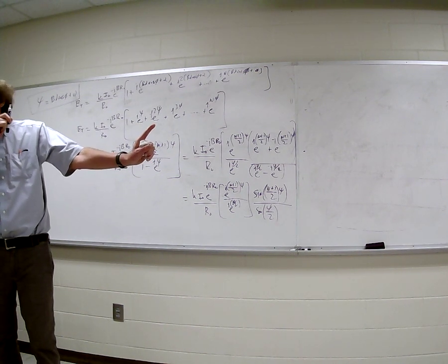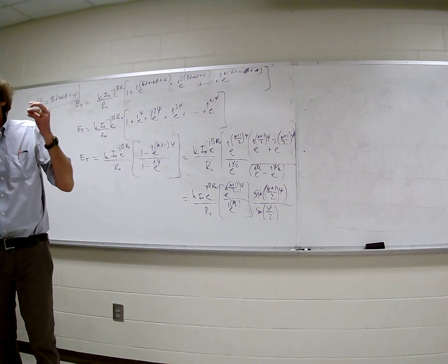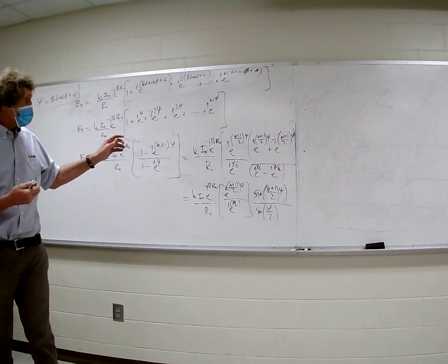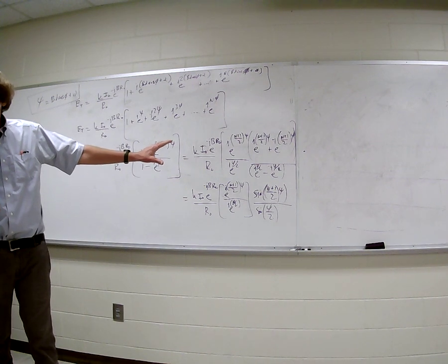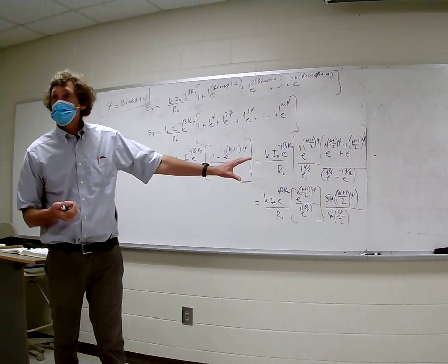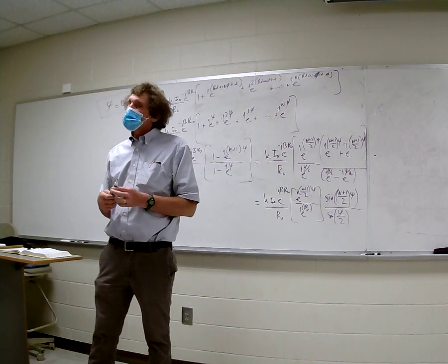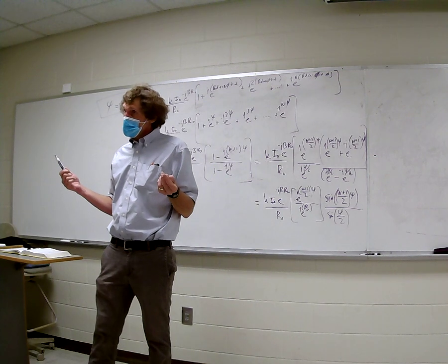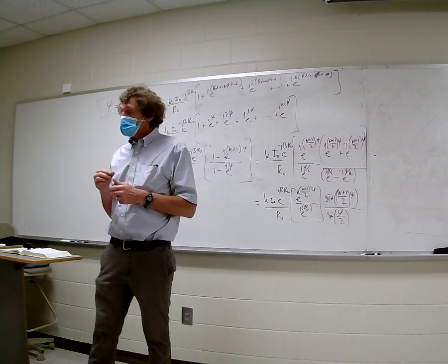If all of them were short dipoles, I'd multiply it by the electric field from a short dipole. And if you take the isotropic radiation characteristics of an array and multiply it by the actual antenna that you're using, you get the total electric field. I'll put this stuff on one note. And if I wanted power, if I have the electric field, I square the electric field, right? And divide by 2 eta, I can get the power density. I can get the normalized power.